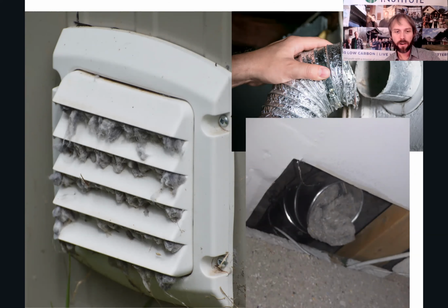Looking at our dryers, look at this, right? Dryer maintenance, right? We have to maintain dryers, or this is what you're going to get. This is what your clients are going to get, right? We're talking about another hole in the wall, another hole for air to leak, another hole for pests to come in. So we're looking at health, comfort, and durability. Down here is a picture of a house I had where we got rid of the ducted dryer and just stuffed that hole up and sealed it from the outside, to stop the air leakage and the moisture and pest entry.